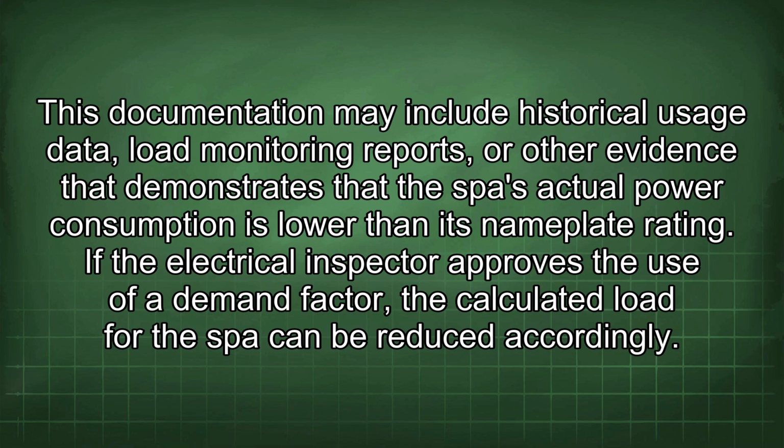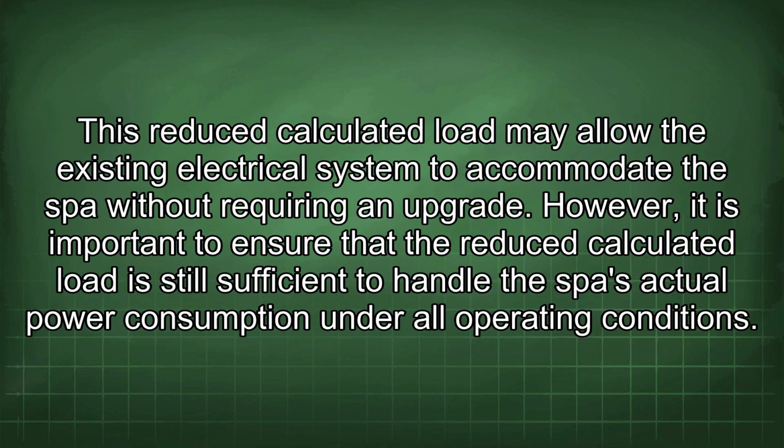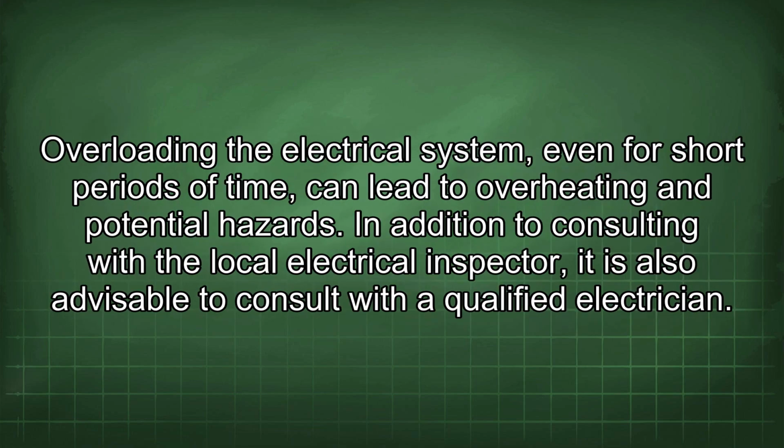If the electrical inspector approves the use of a demand factor, the calculated load for the SPA can be reduced accordingly. This reduced calculated load may allow the existing electrical system to accommodate the SPA without requiring an upgrade. However, it is important to ensure that the reduced calculated load is still sufficient to handle the SPA's actual power consumption under all operating conditions. Overloading the electrical system, even for short periods of time, can lead to overheating and potential hazards.